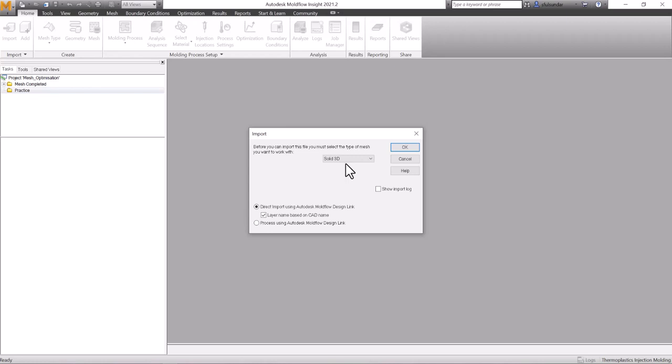Well, dual domain mesh always lays the base for the 3D mesh. There is an option to directly import the CAD model and run the simulation. The algorithm automatically converts that surface into the 3D mesh, but again in the background it converts the CAD model into the surface mesh and then gets into the 3D layer mesh. We'll also see some of the options while importing.